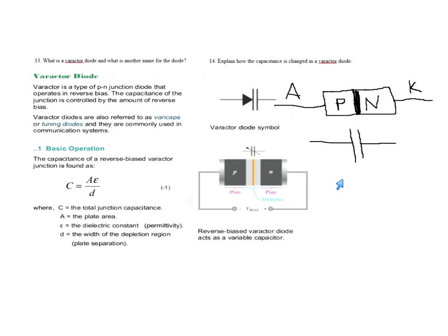Normally, we ignore that internal capacitance when we use a diode in the normal fashion, or as a Zener, or as an MOV. But a diode that acts like a capacitor, we can take advantage of that feature and put it into a tuned circuit. You recall, we talked about tuned circuits last week. You put a capacitor with an inductor, you're creating a tuned circuit.